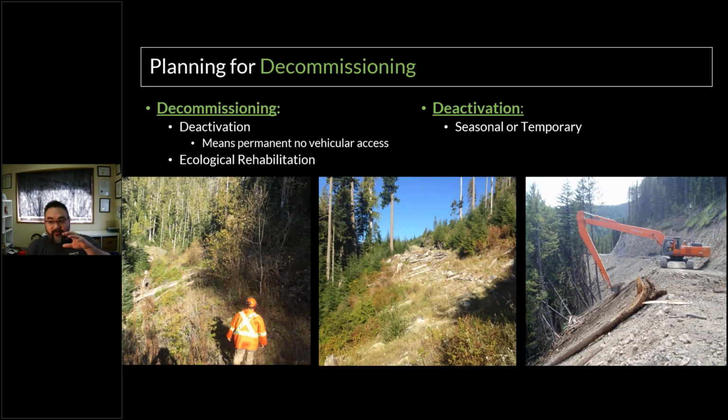And in deactivation or decommissioning specifically, we talked about it a bit earlier about how steep am I going to cut that so I can figure out whether I want to end haul material or not. If I'm a temporary road, I might cut steeper or temporarily store my fills, so when I deactivate, it's easier. So, for example, on the picture on the right, if it's a temporary road, we don't want to have long fill slopes and be required to have a specialized excavator to retrieve those when we go to deactivate.